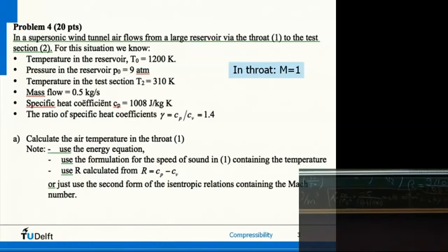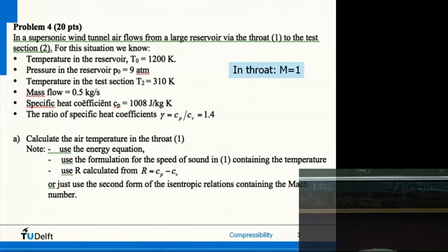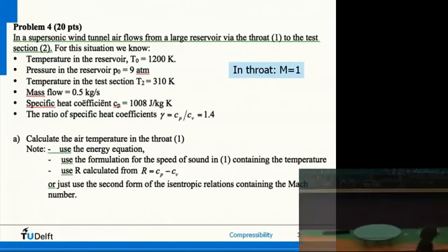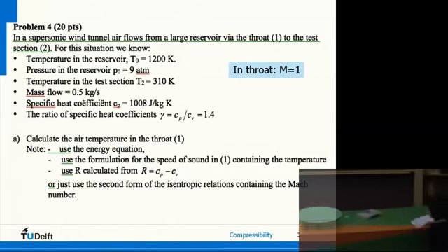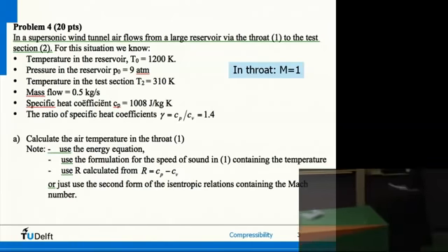So the area is like this. So really a very strong contraction, which you will see quite often for supersonic flow. If you look at our hypersonic wind tunnel, we have a wind tunnel where we can obtain a speed in the test section of Mach 11. We have a very strong contraction ratio. Also the flow expands very strongly, and then the flow condensates, so we can only measure for 1 millisecond. Is this clear? Any questions about this?